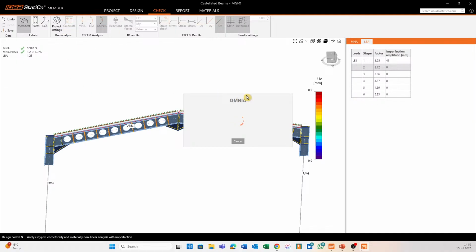So we might find ourselves in a position again where the applied loads are not at 100% because the stiffeners are not sufficient. But then we will try our very best to get that plate on the bottom flange of the I section. Actually, we'll try our very, very best and then run the analysis one more time. So really hoping we get to that before our time runs out.